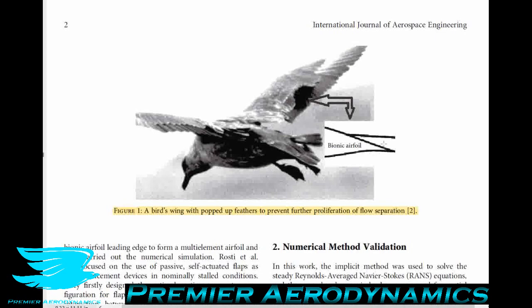And they have a little schematic here showing the idealized situation of this, so the idealized cross section, where you have the trailing edge, which comes down as a typical trailing edge on an airfoil. But then a little bit further upstream on the suction surface of this airfoil, so the upper surface, you have this additional little platform that comes out, this flap. And they've drawn it as being flat, so it comes straight out horizontally, but it can be at different angles. So these birds, for example, can put them up at different angles, a little bit higher, a little bit lower, depending on their aerodynamic needs.